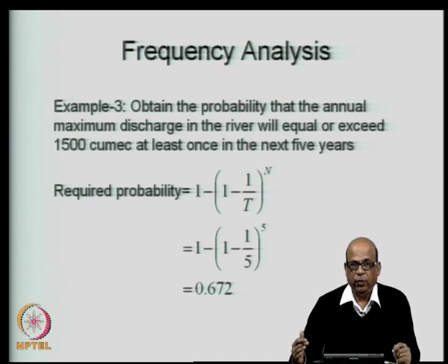And then once we have the correct data, we do the frequency analysis. We introduce the concept of average recurrence interval. We call an event x greater than or equal to x t an extreme event, and then we look at the recurrence, or the time that elapses between consecutive occurrences of such events, and reckon it as a recurrence interval.